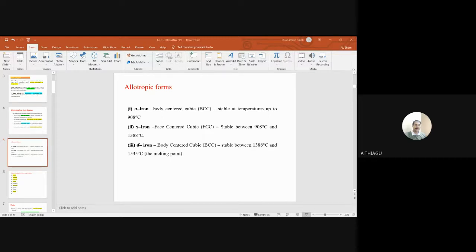After that, the sample should be allowed to cool. Allowed to cool means at a particular point B, you can see the temperature is around 710. What is that structure? Small nuclei of alpha will be formed. Can you see the area? Almost 50 percent ferrite will be formed, and the remaining 50 percent is made from cementite. Once the cementite and ferrite are formed, we can call it pearlite material.